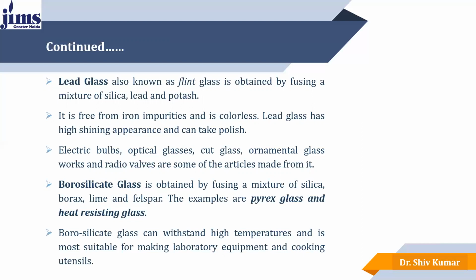The next and the finest quality of glass is borosilicate glass. It is obtained by fusing a mixture of silica, borax, lime, and feldspar. The best examples of borosilicate glass are Pyrex glass and heat-resisting glass.